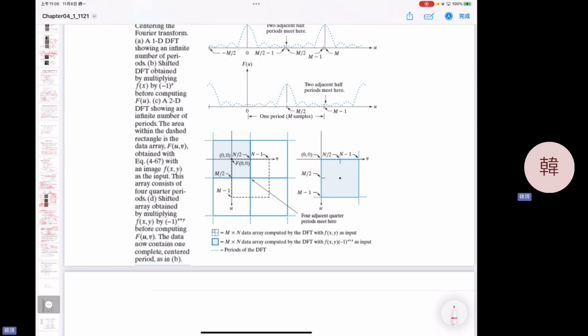Here is the Laplacian operator we performed before, which is a second order derivative. Your magnitude spectrum will be multiplied by this coefficient twice, so you are going to have the square of this coefficient, with magnitude in the horizontal direction and in the vertical direction.